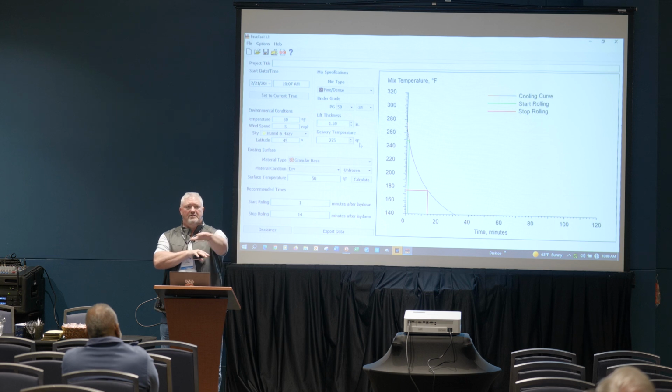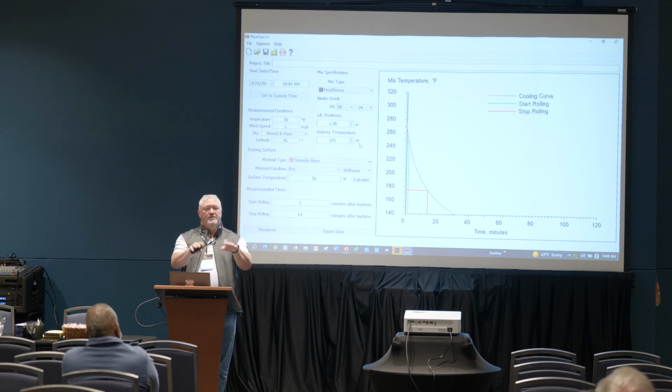front to back to try to cover everything, move them in tandem, echelon. So now you have one roller covering one side of the pavement, the other roller covering the other side. You'll increase your compaction. You might even eliminate having 2 more rollers behind you. You just have one to finish things up because you're going to get most all your compaction with those 2